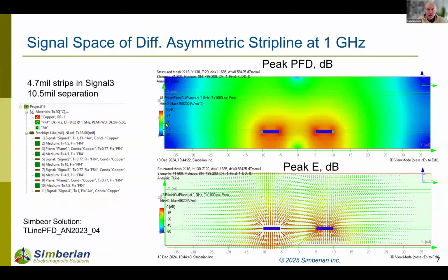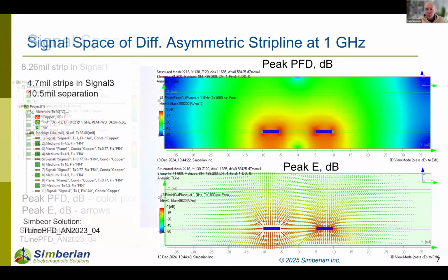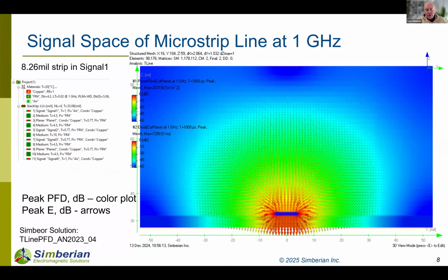But then you see this green area with power levels of -30, -45, and blue is -60 actually, where it spreads even beyond this area here, and the scale here is in mils. So it's quite a wide area, and anything that gets into this area is coupled for sure, and may potentially have crosstalk.